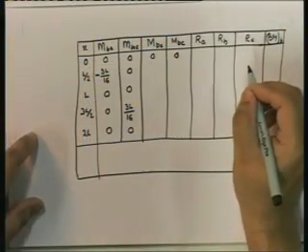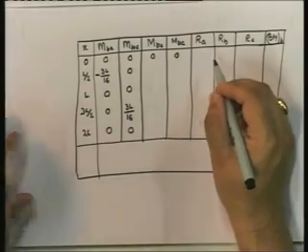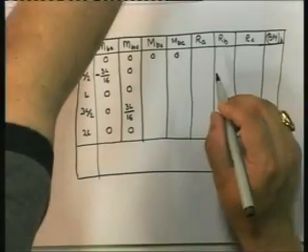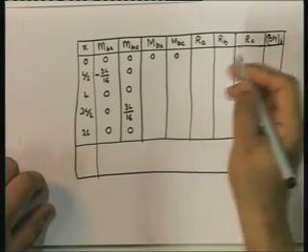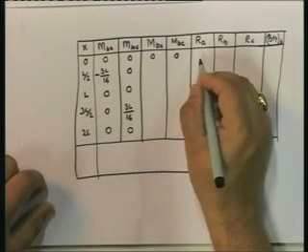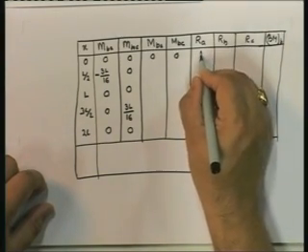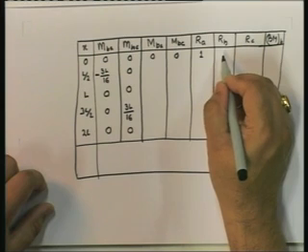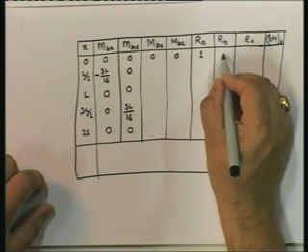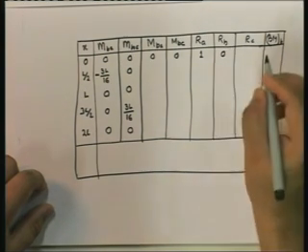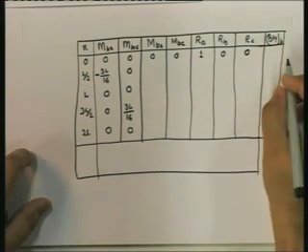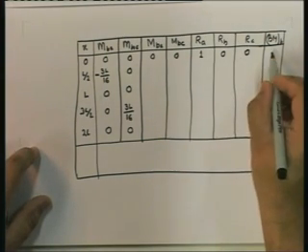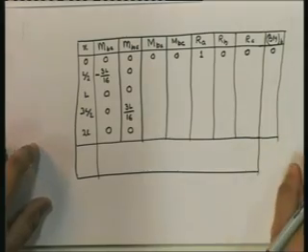So this is going to be 0, 0. Okay, and what is the expression for RA when x is equal to L? Just plug it in. MBA is 0, so you get x equal to L, so RA is equal to 1, and RB is x by L, so that is 0. RC is minus MBC by L, that is 0, and the bending moment is MBA, which is 0.